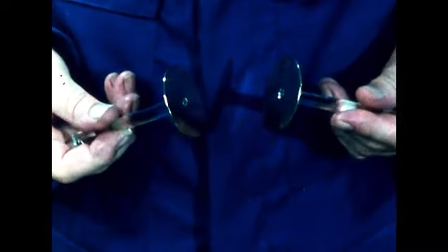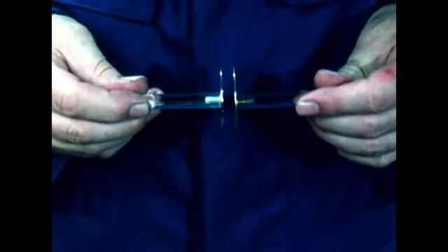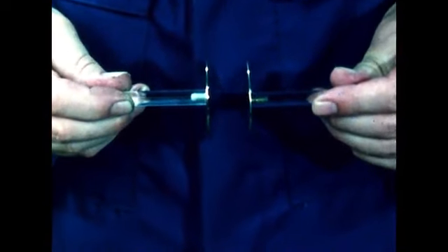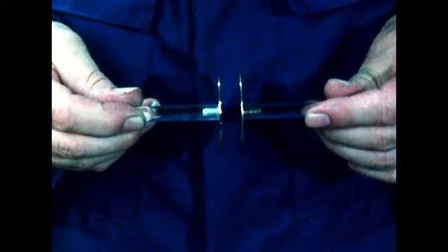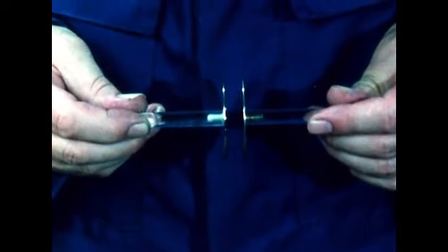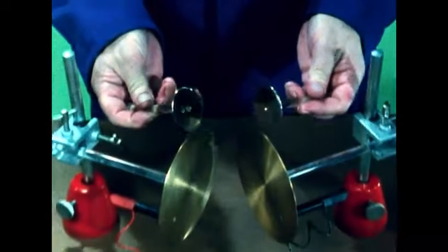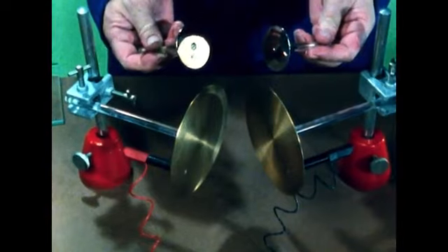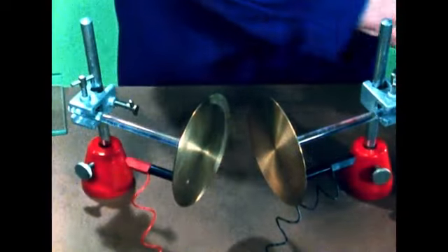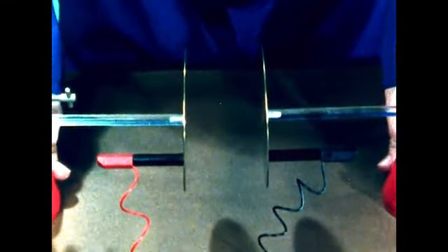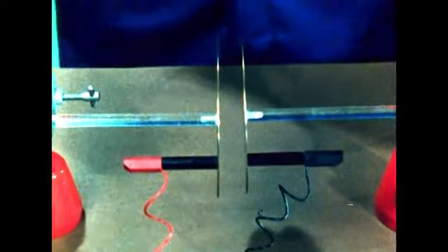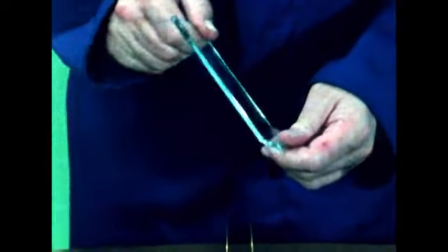Now this capacitor was very simple. It would not be very good at storing a charge. Its capacitance is low. It can be improved in a number of ways because capacitance depends on three factors. First, the area of the plates. The larger the plates, the greater the capacitance, the more charge that would be stored. Next, the distance between the plates affects capacitance. The closer they are together, the greater the capacitance. And finally, the dielectric. Here it's air, but if a better dielectric is used, more charge could be stored. The capacitance would be greater.